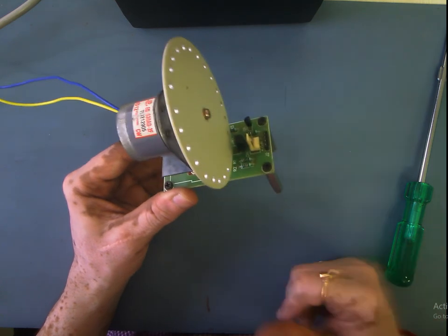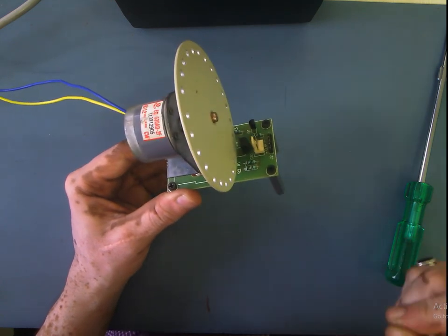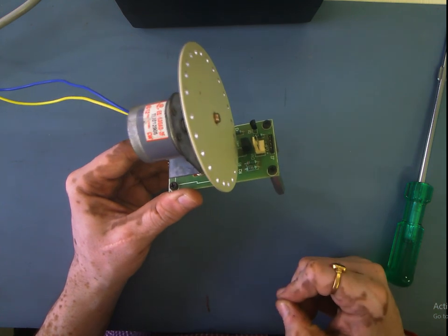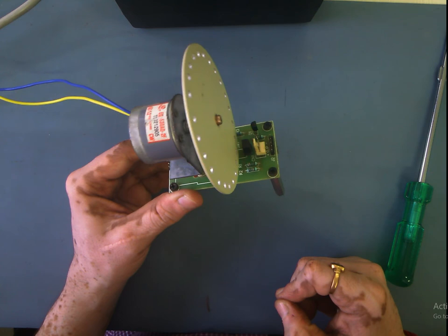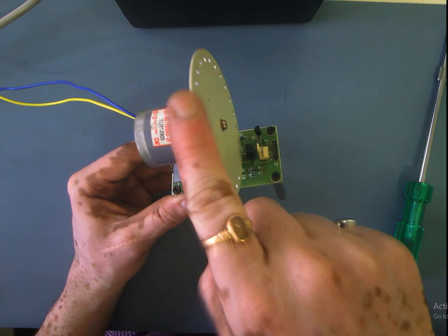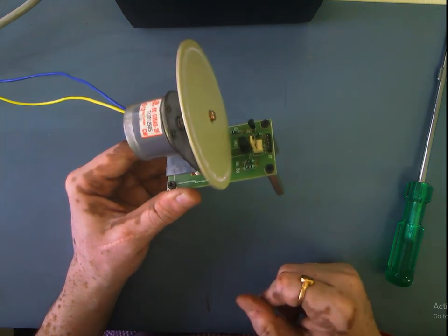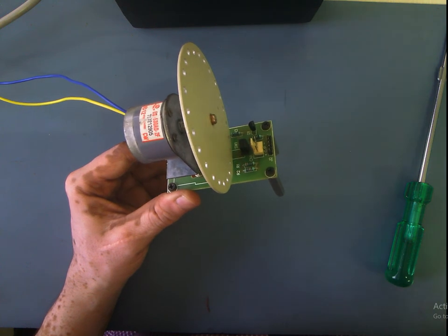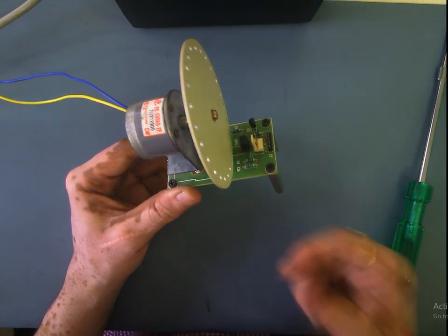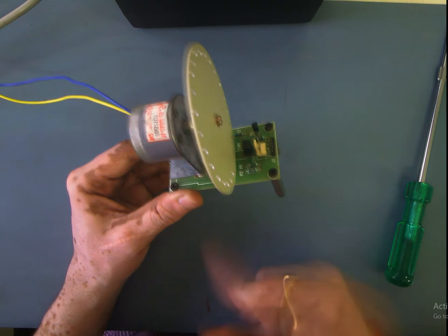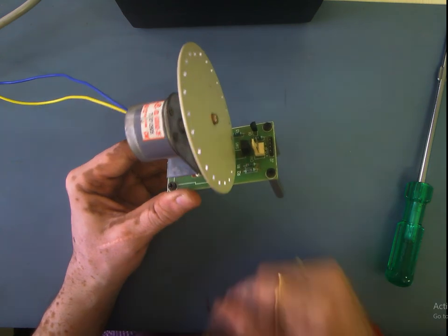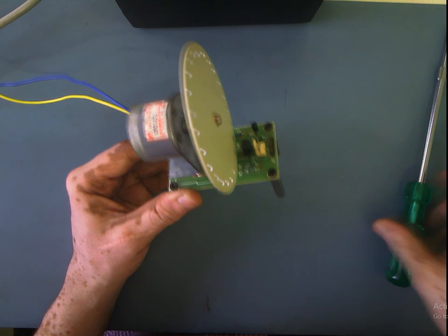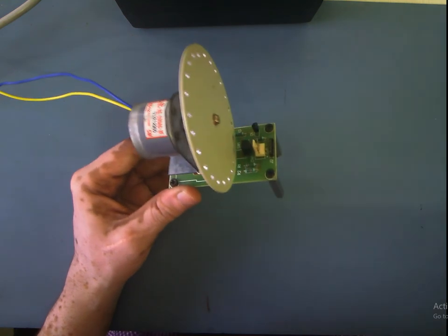What does that signify? If I make proper measurement from the phototransistor, I will be getting a continuous train of pulses. If the rotation is at higher RPM, the pulses will be in such a format that you will have a higher frequency. And if this is rotating slowly, then you will be having a lower frequency at the output of the phototransistor. So this is the basic operation.